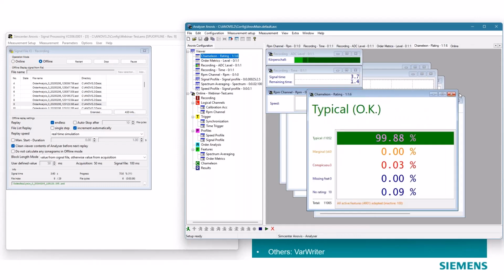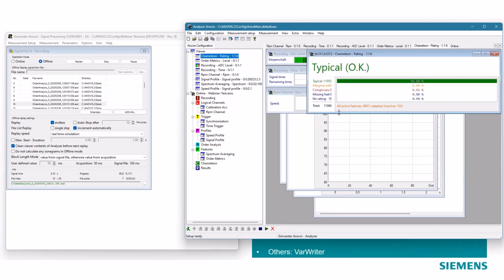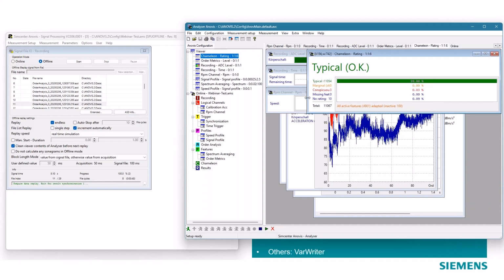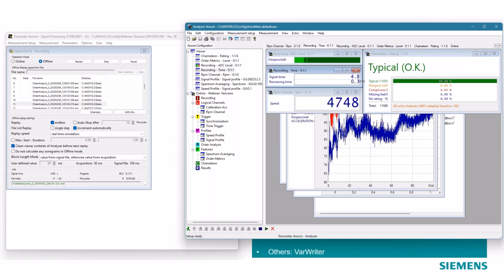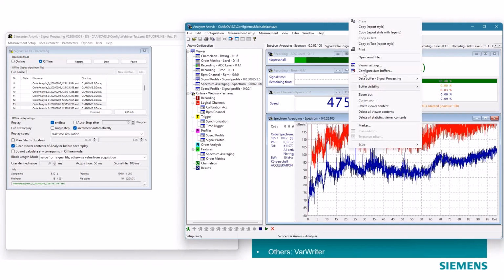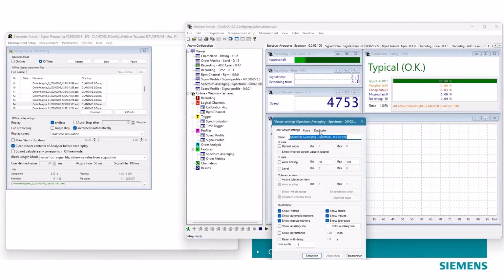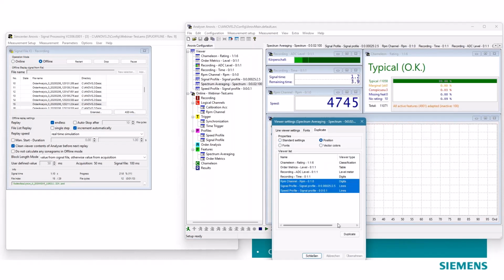Many of our customers do 2 digits after the dot for RPM. Yeah, this is much more precise than the sensor usually is, so this would be enough. But you can set it however you want. Pulses per rev encoders, the usual. Yes, you're right. And then we do the same with the other graphs, and to make it a bit shorter, I can duplicate the position of them. It makes it a bit easier to build this all.